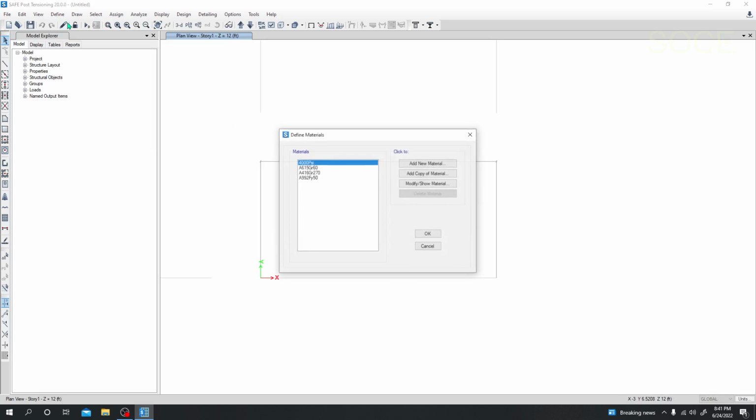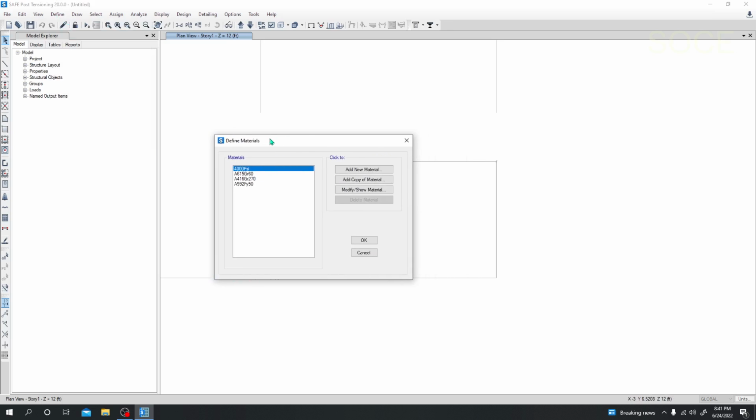I'll go here, define materials property. In a previous lecture I showed you how to define material properties. In this lecture I'll use concrete of 4000 psi and reinforcement of grade 60. If you need to learn how we can change those or add new materials, I'll request you to watch our previous lecture. That playlist is given in the description. I'll just click OK.